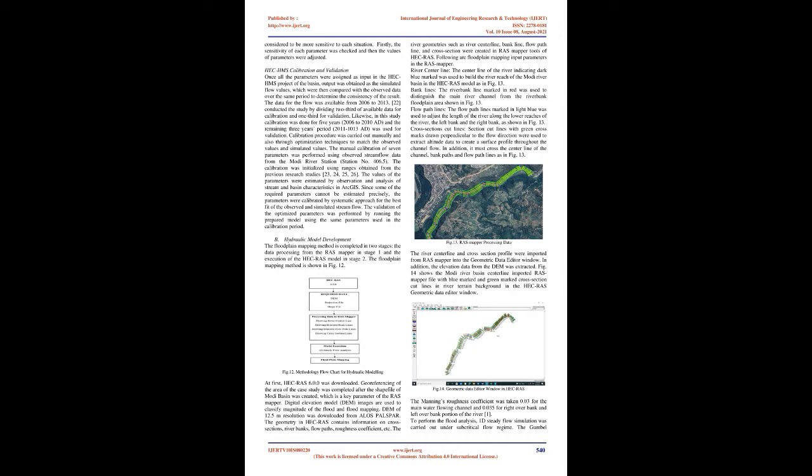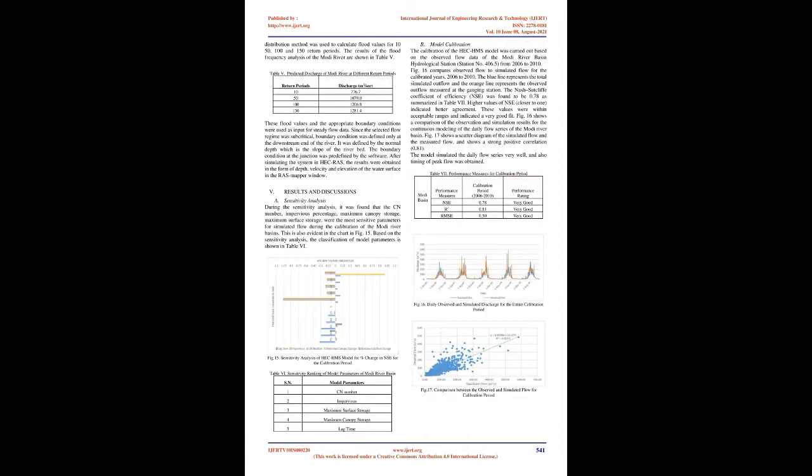Evaluation of model performance. The goodness of fit was assessed using hydrograph visualization and computed statistical performance measures. Factors like Nash-Sutcliffe Model Efficiency, NSE, root mean square error, RMSE, and R2 were the basis to assess the efficiency of the hydrological model. Nash-Sutcliffe, NSE, coefficient of model efficiency was used to measure the goodness of fit between the observed and simulated flow time series.